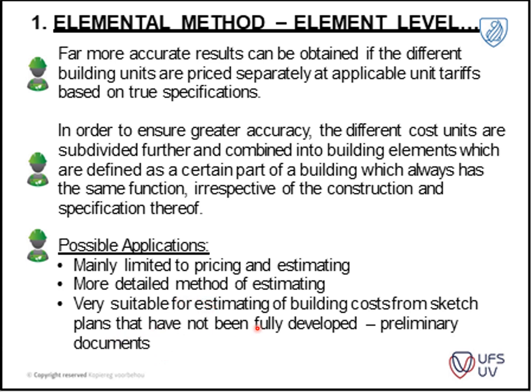Okay, so very suitable for estimation of buildings from sketch plans that have not been fully developed or as your primary document. As we go through the examples, you will see one of the elemental estimates that I'm going to provide you with is one that we did a while ago, where we only had concept drawings. So there were a lot of considerations and assumptions that we had to make when we did that estimate.